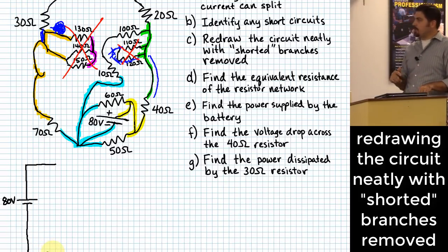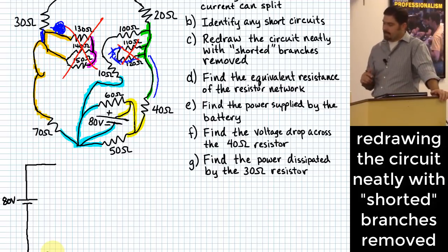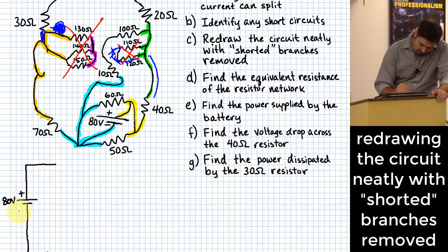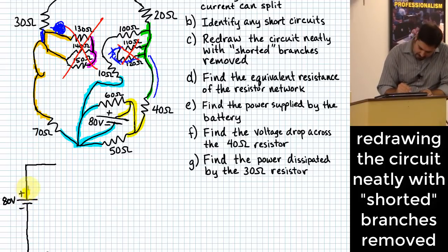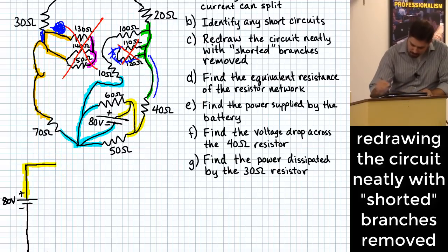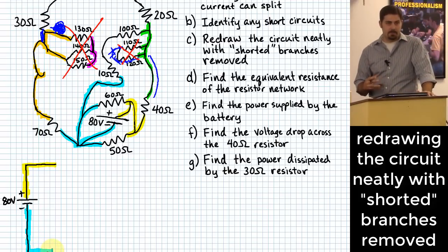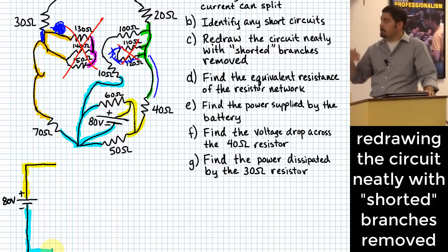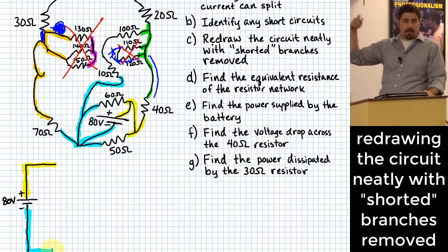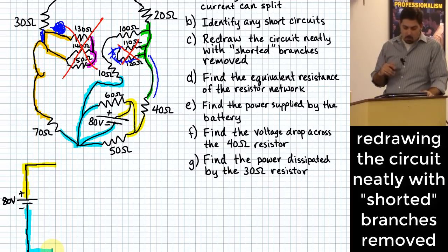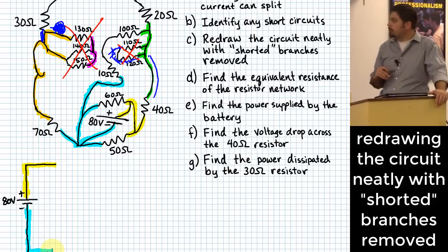Because ultimately what we need to do is find all the different paths that we can get from the positive side of this source to the negative side. And so let me go ahead and I'll start also by saying this is my yellow node that I'm setting up here. This is my blue node that I'm setting up down here. I'm just drawing it in a different way, but they're not different. Those are the nodes I'm representing here. And what I'm drawing up here is an equivalent circuit to the big messy thing. Okay? So what's one way that current could flow from yellow to blue?